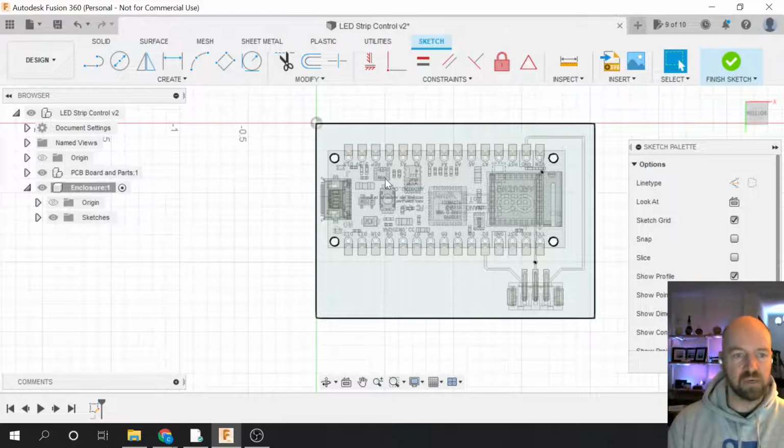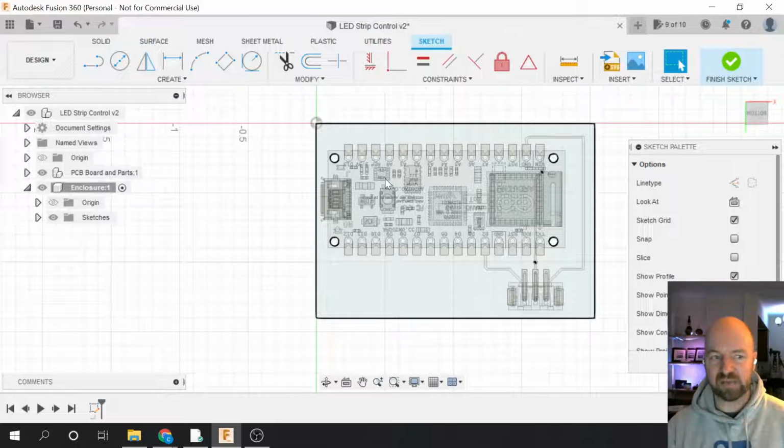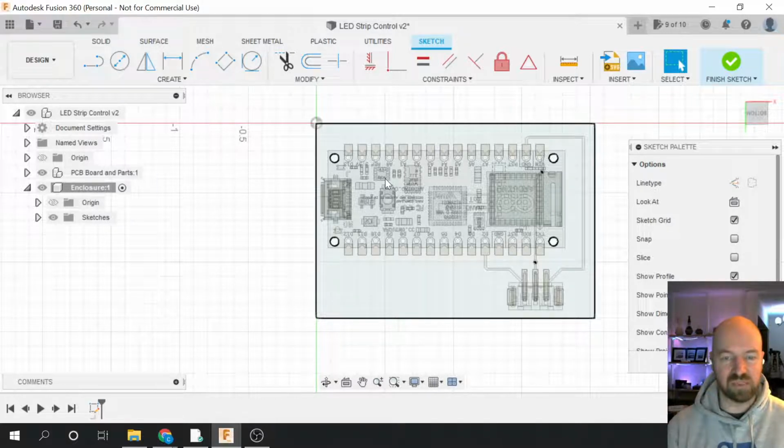Yeah, I would go with capture. Whenever you get that little pop-up that says, hey, do you want to capture the position of everything? It's because we use the move tool, and it just wants to make sure that you want to start from where things are at currently versus where they used to be at. Sometimes I get that dialog box and sometimes I don't, and I'm pretty sure it has to do with the move tool, but I can't confirm that because it seems to pop up sporadically. But I always choose capture current position whenever that pops up.